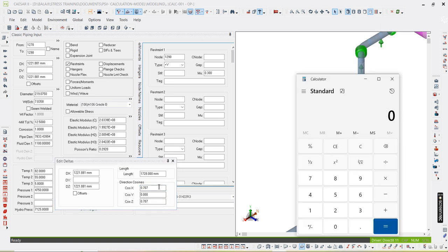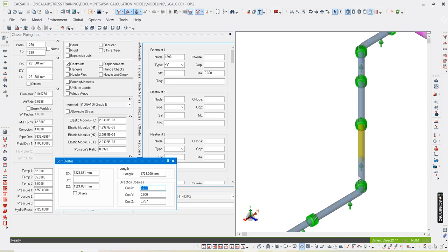So that's value only it is showing, because we have a 45-degree elbow. Okay. So any 45-degree value should be 0.707 only, either in the negative direction or the positive direction. Since the line is traveling in both the positive x and z direction, it is showing positive. If anything is negative, then it will be in the negative direction.